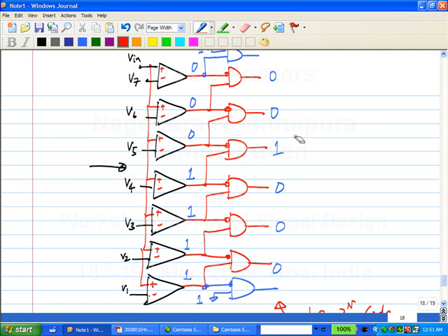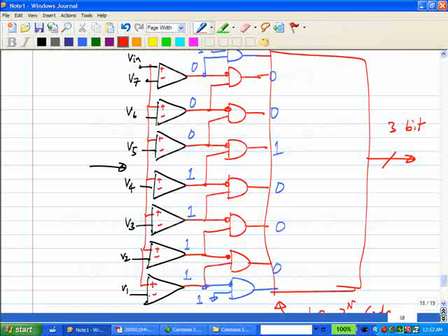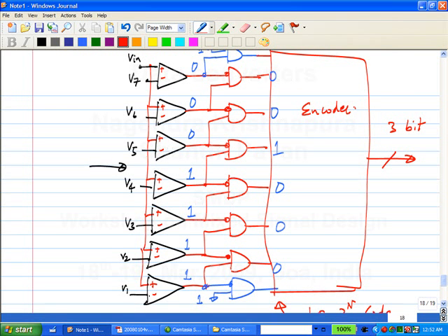So for every bin, you assign a code word. There are 8 bins, you assign 8 code words, which means that you can do with just 3 bits, right? So all that you need to do therefore is to have some logic here, which takes this 1 of 2 to the power n code and generates from this a 3-bit word. Okay? What do you think this is called? The encoder, right? This is straightforward to do. Most likely all of you know how to do this. This is just combinational logic, that's all. If this particular wire is high, in what bin does it lie? 0, 1, 2, 3, 4, right? So you put out a code 100. That's all that you need, correct?